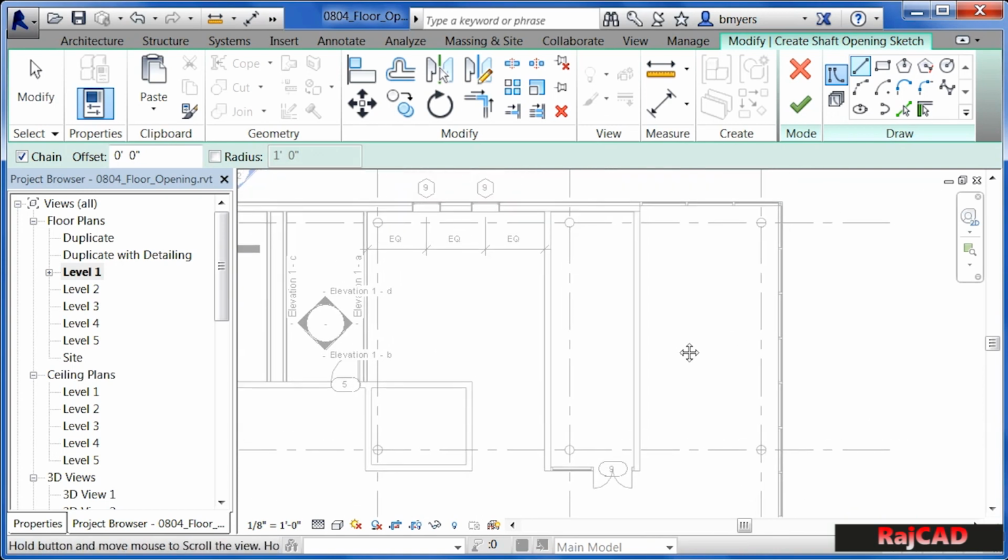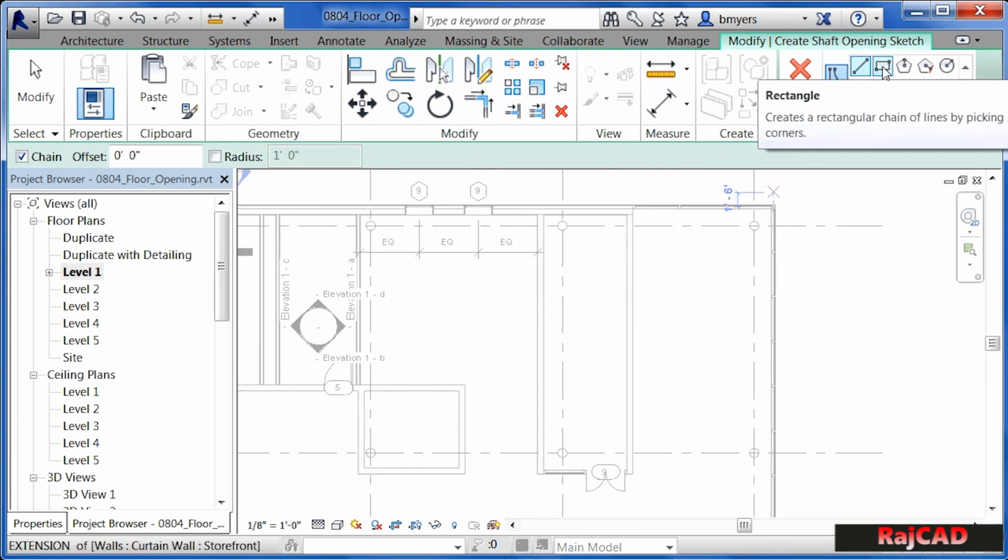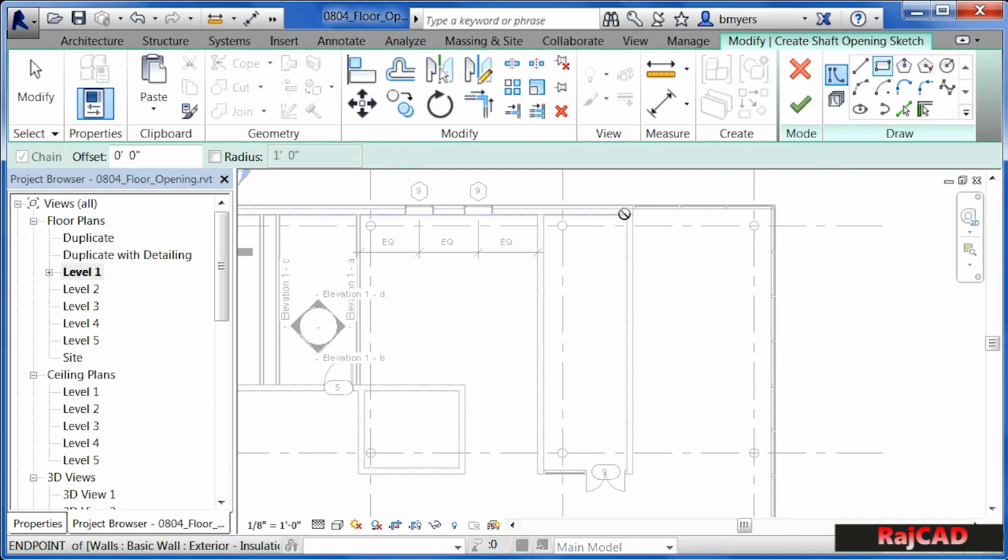After selecting Shaft, pick your Rectangle tool off of the list, click one of the upper corners of the room, then draw a rectangular shape. The exact dimensions don't matter so much, just make it somewhere between maybe 19'6" and 20 foot. We can always adjust this after the fact when it comes time to place the actual staircase, and then click when you have that rectangular shape in place.